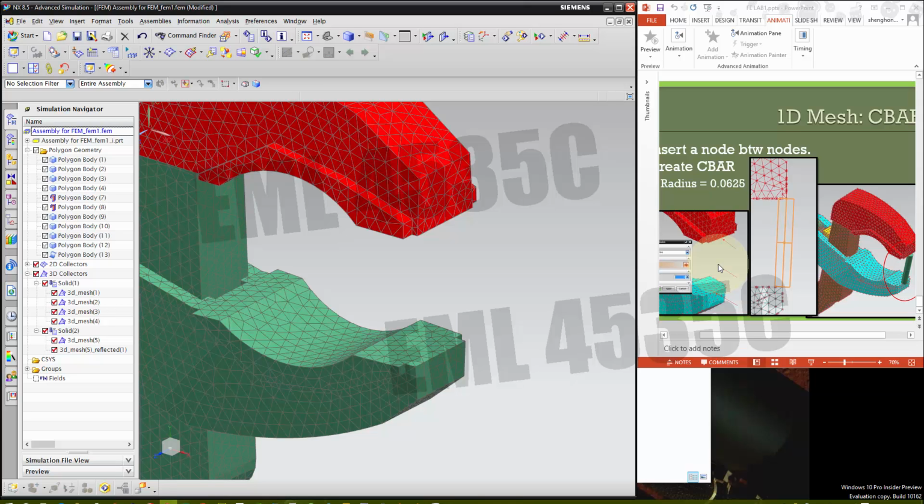Okay, we will apply a fixed constraint on this node. So when you have the results and do an animation, the two jaws will come together towards this node. It is a little bit easier for people to conceptualize the results of your simulation. Okay, so it's more like the real world. They're binding together towards the center.